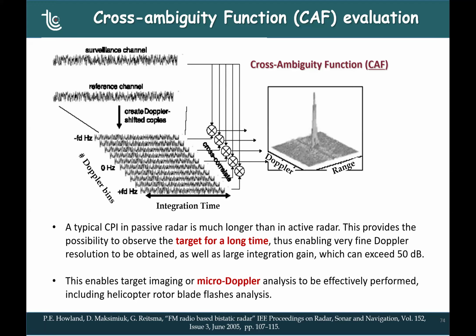detectable. And since we have this long integration time, we have this very high Doppler resolution, then we can even see the micro Doppler. So we can perform micro Doppler analysis, we can see the very fine changes in the Doppler. And we can also, for instance, see the flashes of the helicopter rotor blade.